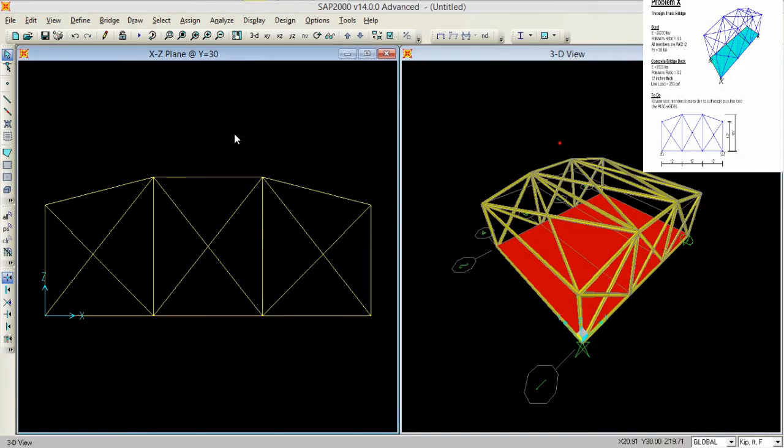So now what to do, I have to assign the loads. Actually one other thing, at the back side I do not introduce the supports. Look at here, on the front side the supports are here, so I need to add the supports over here. All the supports has been provided. So now what I had to do, I had to assign the loads.